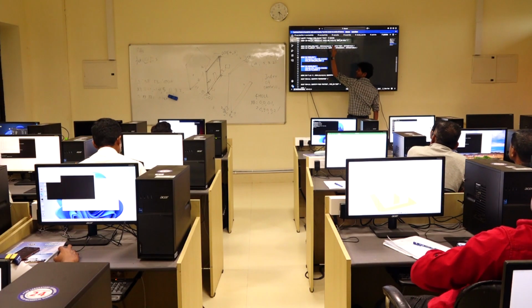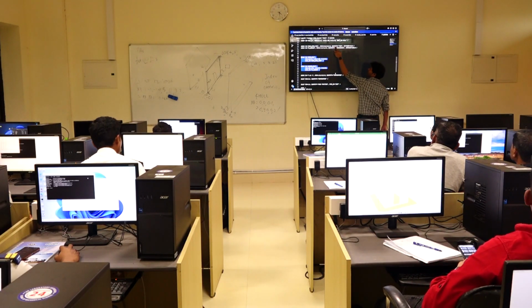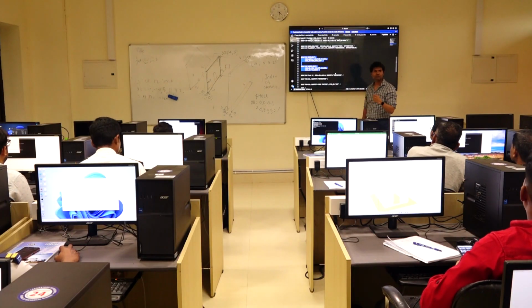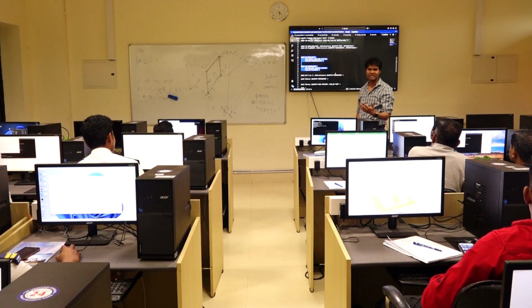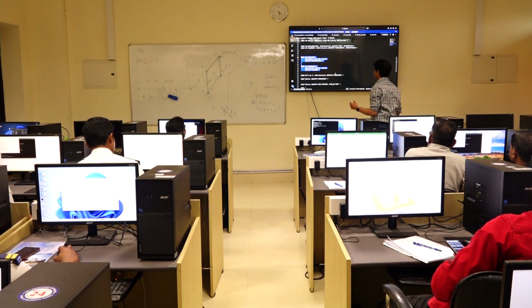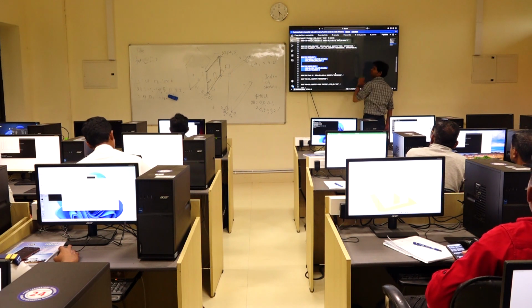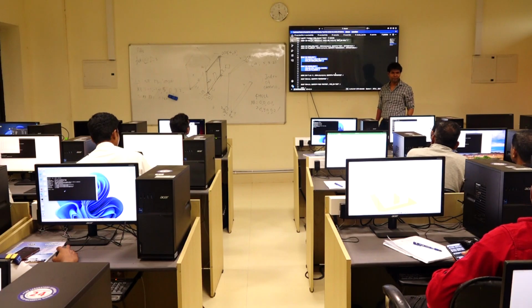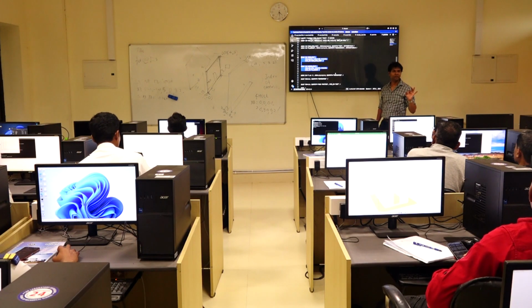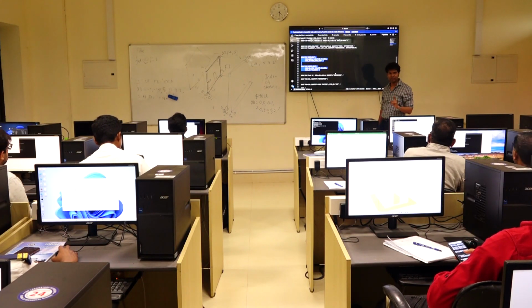You can place that device like a sensor at a certain location, and then what is your parameter to open the door? Your parameter here is time based. So you are going to say that quantity is equal to time, set point is equal to 40. So it's going to open the door at 40th second, no matter what. Right now, your door is open at 0th second. We don't want 0th second. We want 40th second.